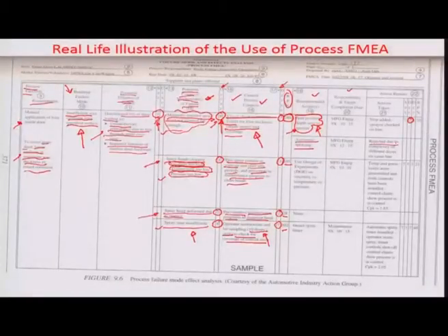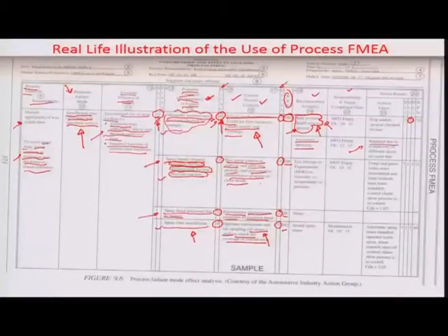There is not a single model production but mixed model production in such lines, and handling such a fully automatic system may be a problem, and therefore this idea is rejected completely, and the idea for the positive depth stop has been implemented. So for the process control of the test spray pattern and also the spray head clog problem, the quality engineer suggests the use of DOE, or design of experiments, to get a proper value related to the viscosity, temperature, pressure based on the operating conditions or the operating temperatures in which this process is carried out on the line.